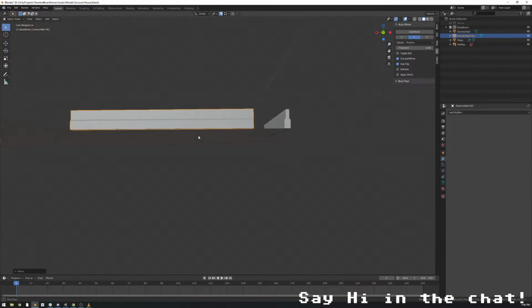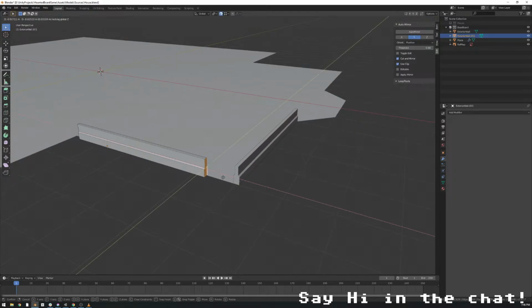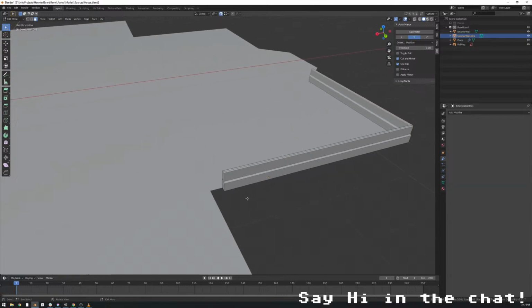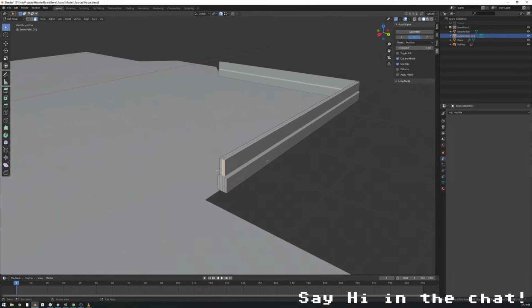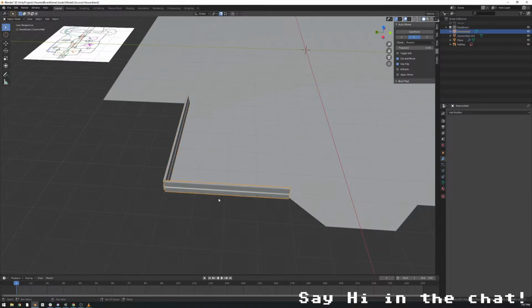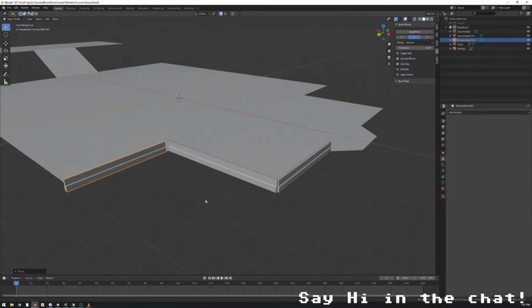We're gonna see if we can just line these guys up real quick. We'll deal with making it pretty later. Grab these faces. Boop, boop, boop. Grab X. Snap to there. Shift D, Shift Z. Get it close. There we go.